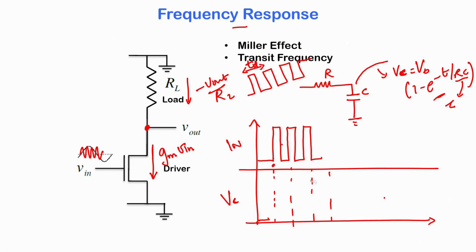So now you have a pulse that has got a higher frequency, you have increased the input frequency of the pulse. So now the capacitor tries to take its time, it has got a time constant of RC. RC has not changed, you have only changed the time period of this pulse. So it is going to try to climb, but you have not given it enough time to charge fully. So it is going to climb till here, and then it has started to discharge, and then it is going to climb till there and started to discharge. And therefore earlier the capacitor was climbing a lot more, it was getting charged a lot more, but now we are allowing it to charge only a little.